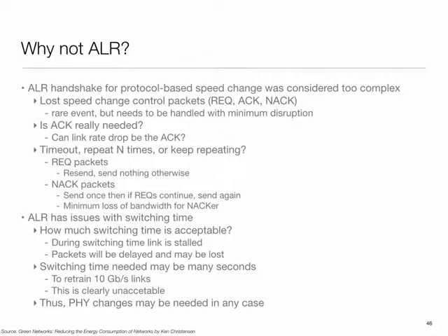So what happens at the physical layer is, as we go to higher and higher speeds, the physical layers have to learn the channel characteristics. They send some training packets, they learn the channel characteristics, they adapt the filters on either side, and then they operate on that. So every time you change the speed, all of that has to be redone, and that was felt not to be a worthwhile endeavor.